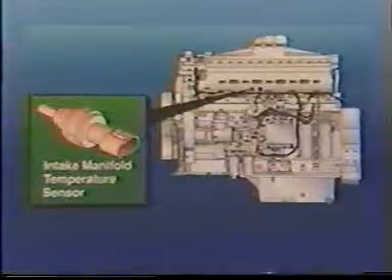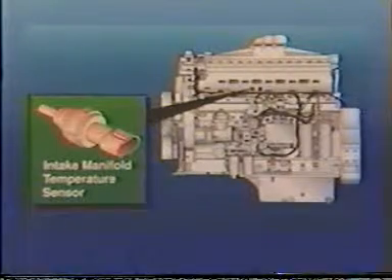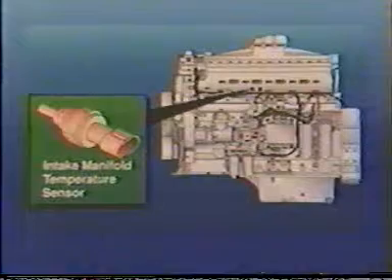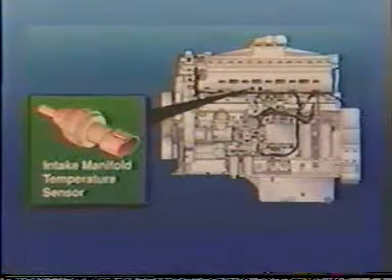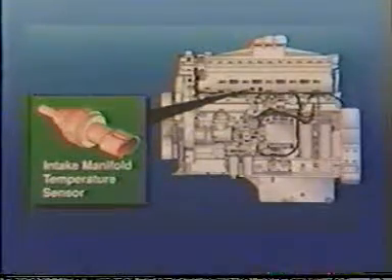The intake manifold air temperature sensor is mounted in the aftercooler housing and measures air temperature after the cooler core. The information this sensor obtains is utilized by the ECM to help make decisions for timing and engine protection.